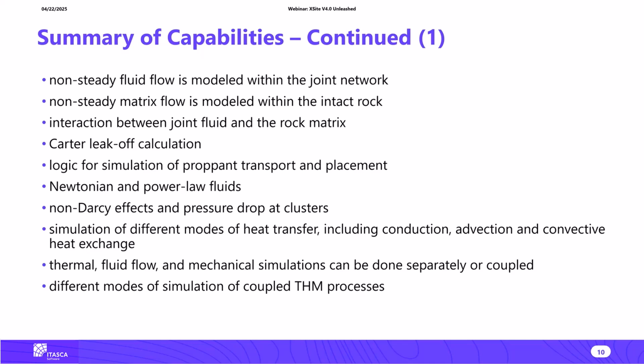It can simulate non-steady flow in a fracture network, but also in the matrix, and the flow in the fracture network and the matrix is fully coupled. On the other hand, since this is typically used in the oil and gas industry, we can also simulate leak-off using the Carter leak-off calculation. The purpose of the model of matrix flow is to have a general model for simulation of the leak-off, but we can also represent the leak-off using the Carter leak-off calculation.